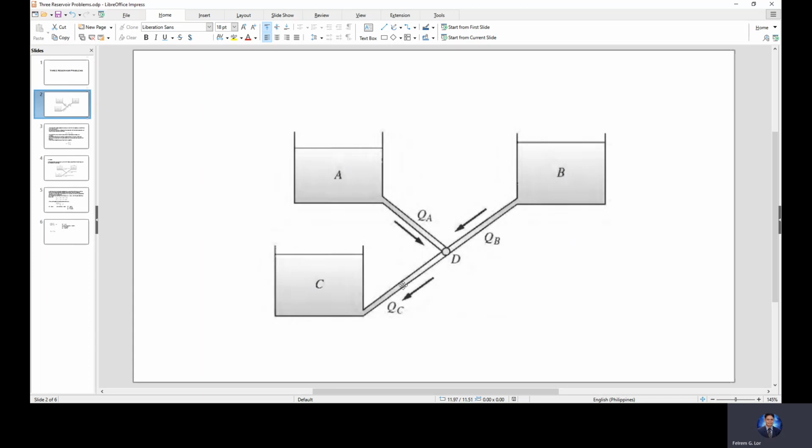It may be a small pipe, or it has large losses, or whatsoever, so the flow from D to C is slower and the flow from B to D is stronger. So instead of the water flowing from A to D, it flows from D to A, going up. Instead of the water going down when it reaches the junction, part of the water goes up.